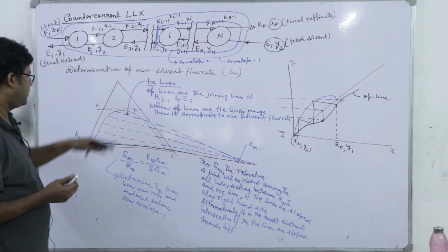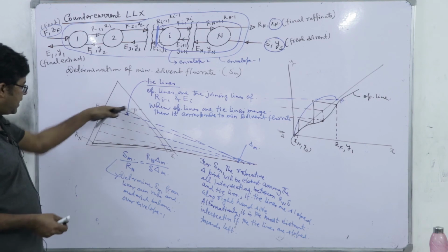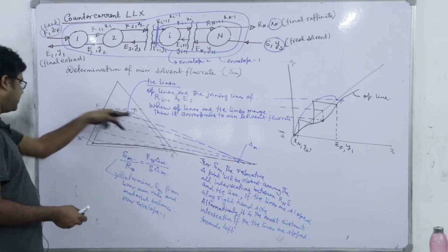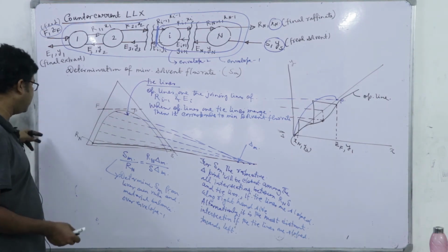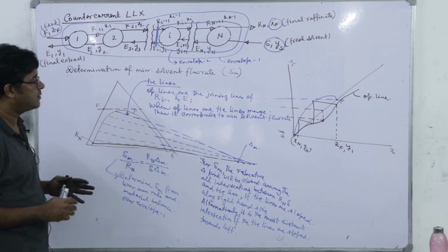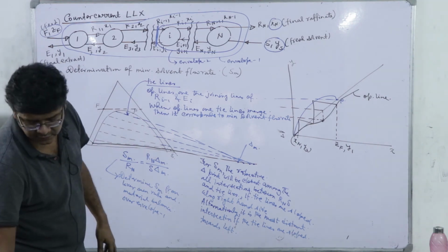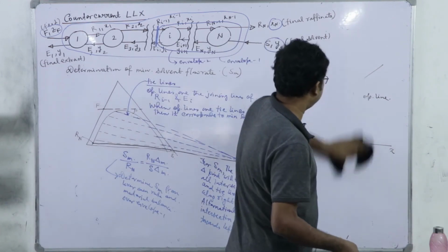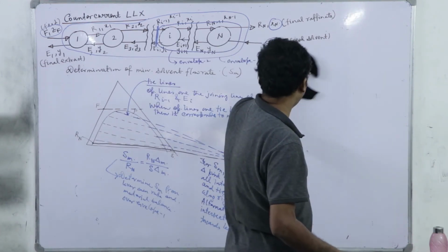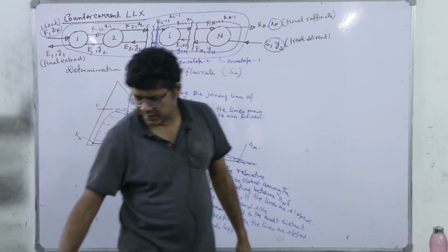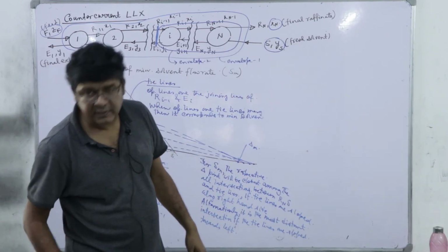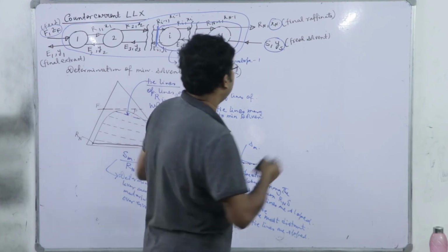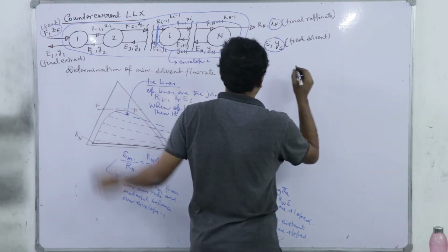Right. So, if the tie lines are inclined like this, it will intersect the Rn and S on this side, and in that case it will be the farthest one. I am not going into the detail of the theory because it is not required that much, but more importantly we will discuss now what will happen here if I have an immiscible carrier and the solute solvent combination.